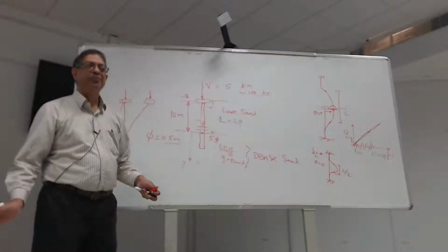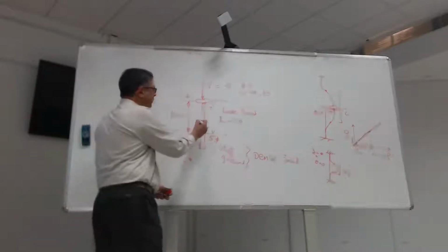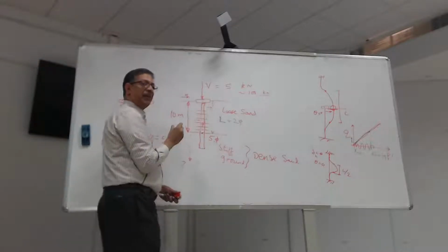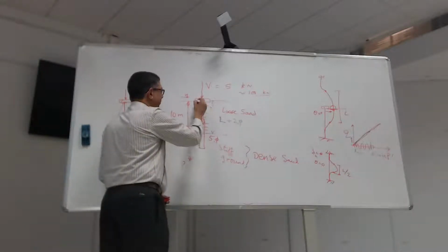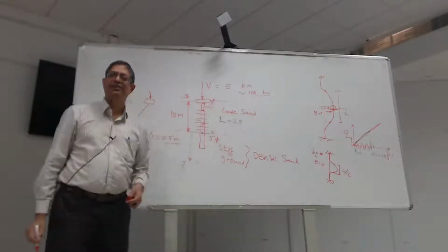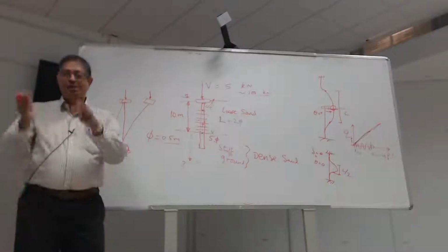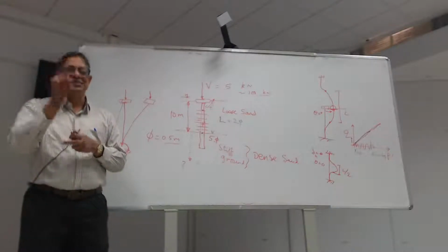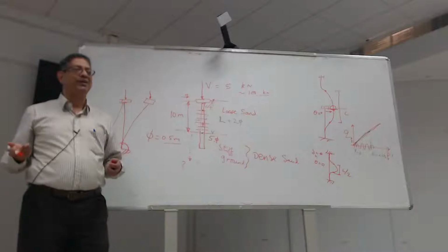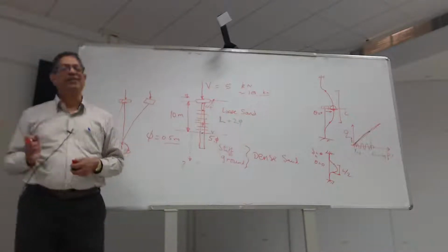Soil says no. So it works its way up, up, up, until a point where it's easy for the water on the surface to come in and destroy my suction. Once the drainage distance is close enough, I can't keep the suction that's needed to hold the pile in place.